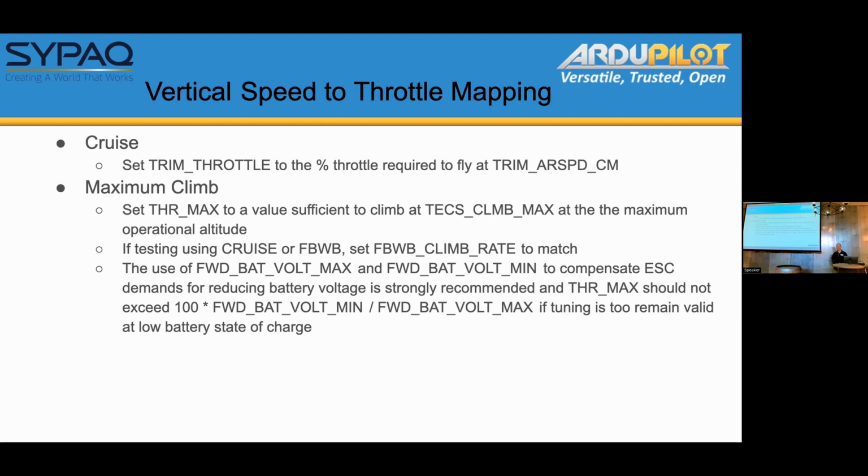Well, we currently have the capability to, so the answer is yes, we could, but you have to make an assumption about the pack minimum voltage. And the problem is, if you have a lithium polymer pouch cell from manufacturer A, they may specify a minimum voltage, never go below 3.4 or 3.3 volts per cell.